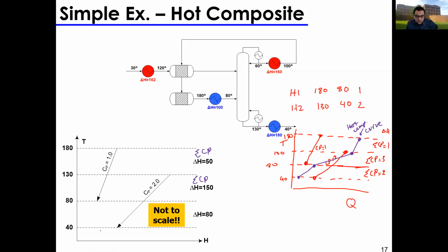Of course, you can do it using delta H if you want. So instead of really trying to draw the slope, I can calculate the delta H and then go, okay, this is my starting point here. So I need to move by a delta H of this much, and I drop the second point, and I need to move by delta H of this much, drop the third point. Whichever way is simpler, whichever way works for you. I find the slopes work better if you're using graphing sheet. Maybe delta H works better if you're using Excel.